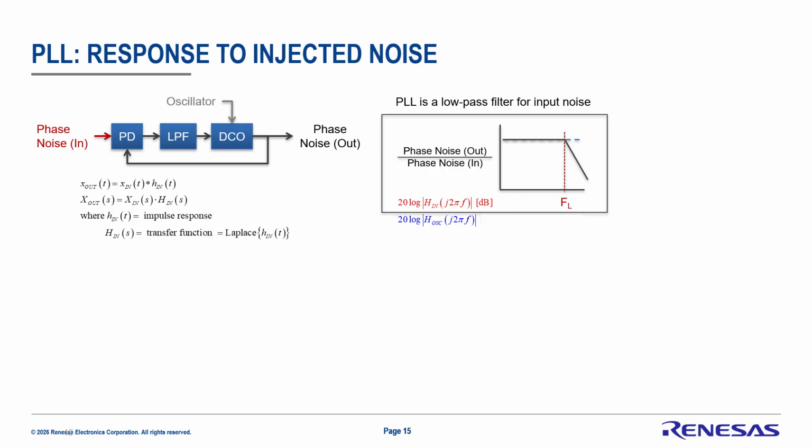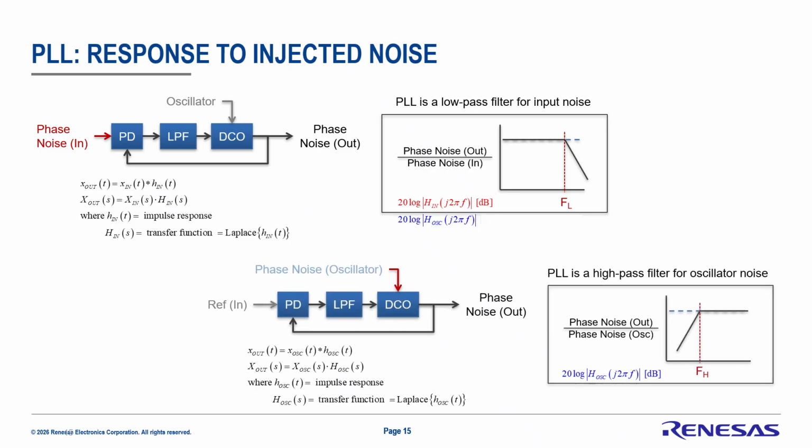The resulting clock must meet phase noise per a typical target physical layer clock, which is like an Ethernet SerDes or an RF clock. The local oscillator attributes some of that noise as well, but it effectively acts as a high-pass filter onto the output clock. So this means any high frequency noises coming from the local oscillator will immediately pass through onto the output.